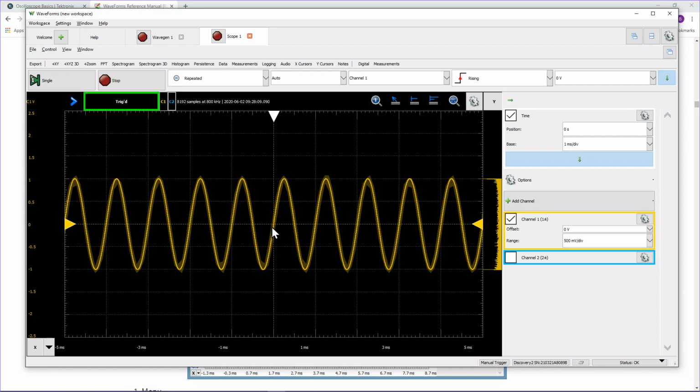From here to here, that's one waveform, and the frequency, which is 1 kilohertz, 1 over frequency is the period of the waveform. And you can see that down here, each of these scales, this starts at 0, this goes to 1 millisecond for a major division, 2, 3. So each of the major divisions is equal to 1 millisecond. This 1 kilohertz frequency means that this sine wave completes a cycle, or one waveform, or one cycle of it, happens in 1 millisecond. And I can change that too.